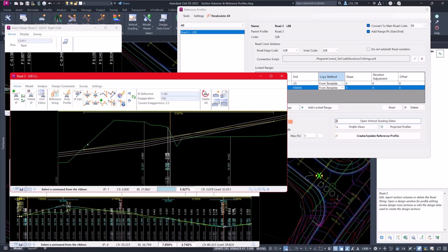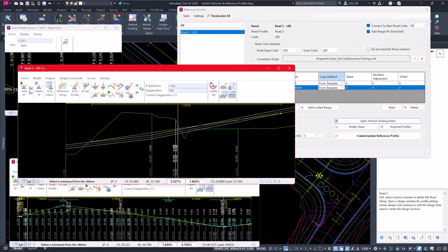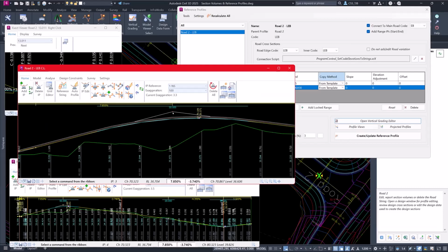It has also anchored the beginning at my matching code, which is up here, that connects to the main road edge, the EB. That's anchored to the EB that's sitting on my road 1. It's then specified the zone of influence, which is my 25 meters here. That's the IP it's thrown in here. And then the IPs beyond that are all locked.